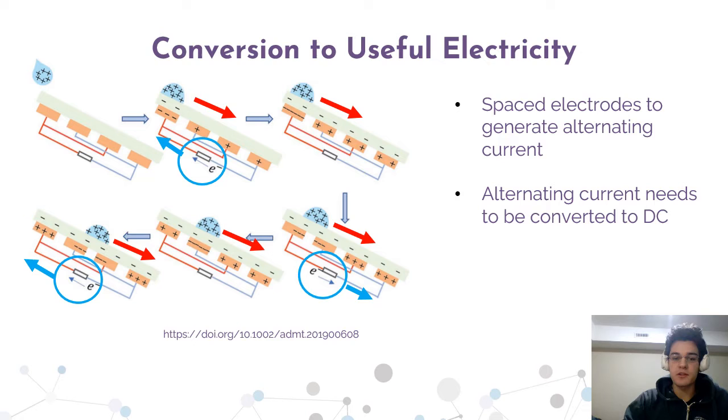Of course, this isn't the full story of how TENGs can be used to generate electricity. The top surface of the device will need to be a thin insulating layer, with conducting electrodes spaced out beneath the insulator. This insulating layer keeps the charge on the raindrop separated from the electrodes, so the charge on the raindrop doesn't get neutralized. As we've discussed, when a positively charged raindrop first lands on the device, electrons flow to the electrode that the raindrop is over top of.